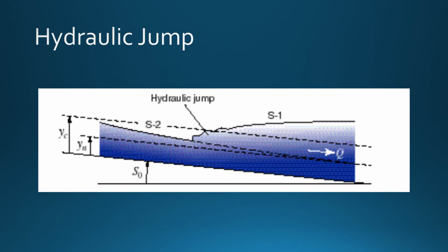Something that is very important that should be of note is the hydraulic jump. As you can see in this experiment, we'll essentially get three different slopes. We'll get slope S naught, which is basically the slope of the system, and it is stationary regardless of what happens. We have S2, which is the water coming from the upstream gate down the system, and this is how you would basically expect water to react by going down any slope.